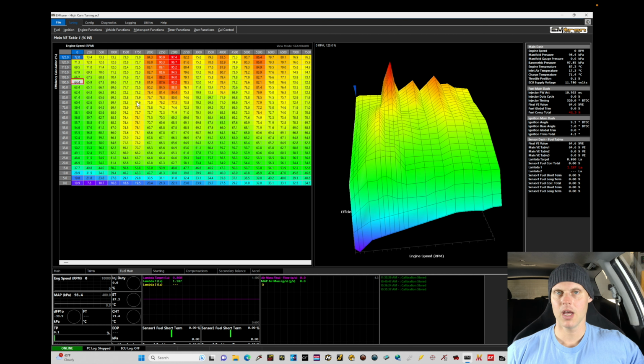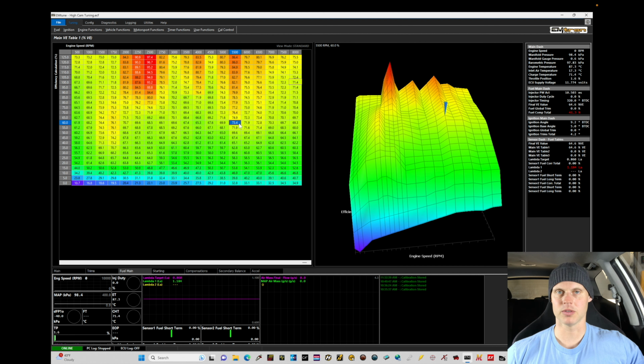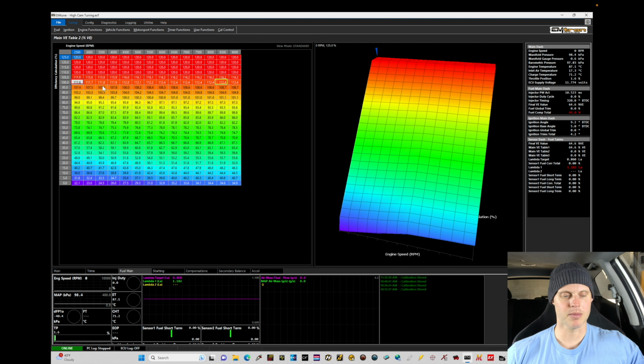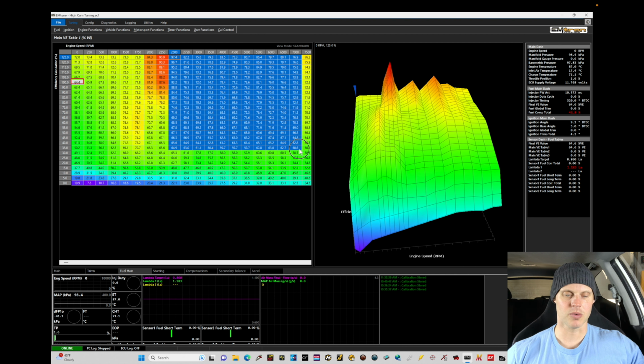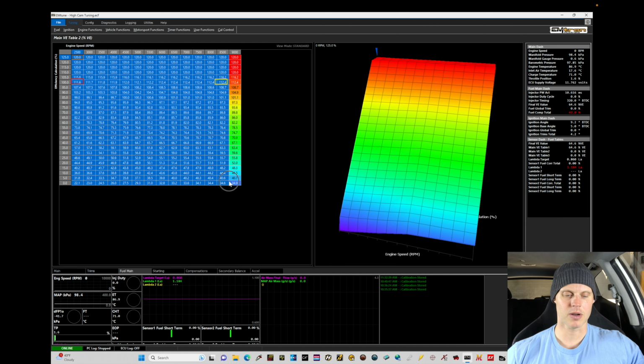And we have to look at our low cam VE values, as these are going to be reasonable starting points of what we can use on our high cam table. So what do we need to do here? I'm going to jump in and take my table 2, looking at my values. It starts here at 2500 RPM breakpoint, ends at 9000 RPM. I'm going to go in here to my table 1 and copy everything from 2500 and above. Even though this table only goes to 8000, we'll copy this. We'll move back in here to table 2 and we're going to paste it.